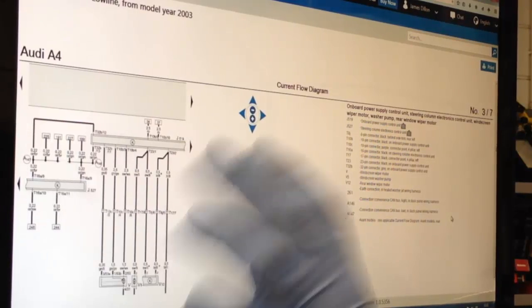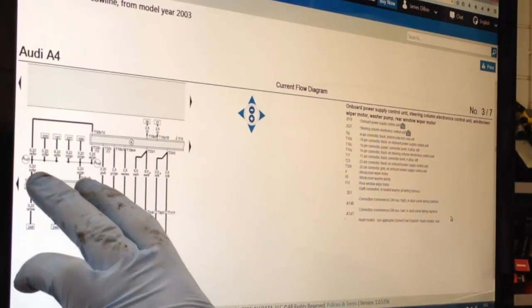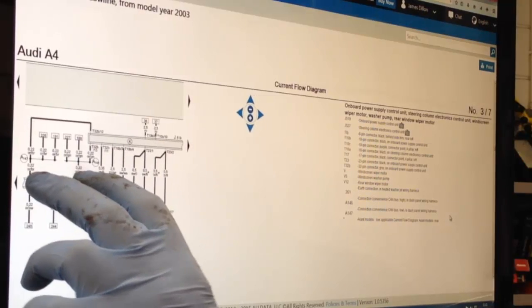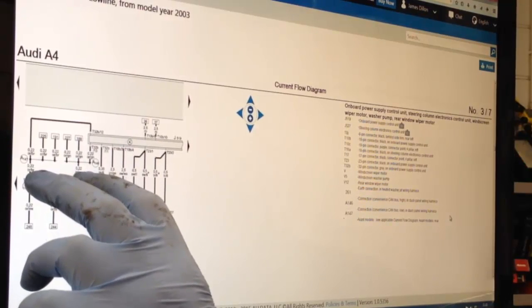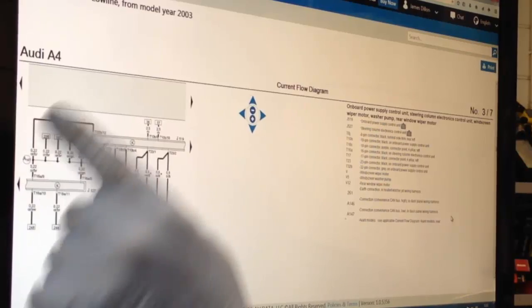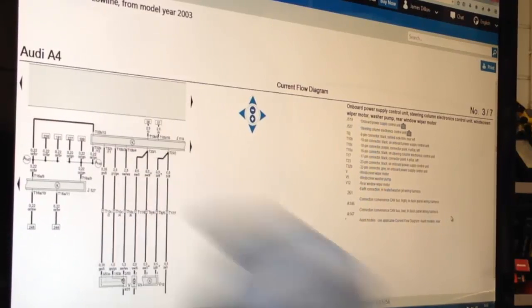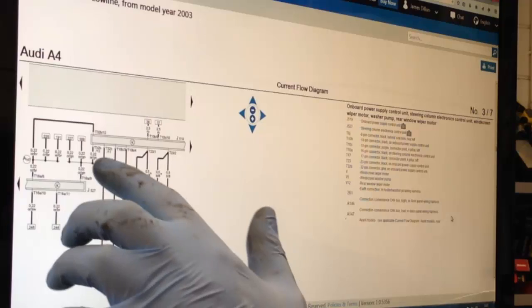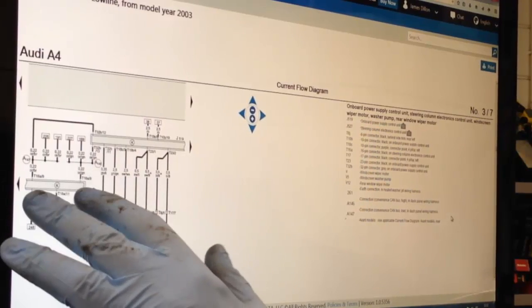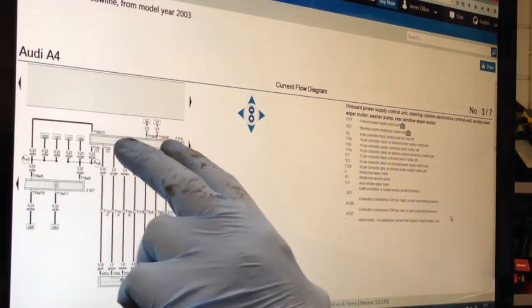These two wires, knowing a little bit about Volkswagen Audi, orange and brown, orange and green, of a very small dimension, 0.22, are very thin wires, and they look like they're CAN wires. It doesn't actually say it, bit of product knowledge there. So we'll have CAN high and CAN low, body CAN, going from steering column to the power supply, and the